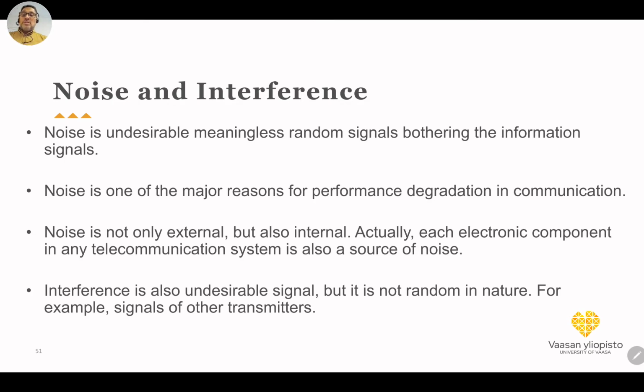But the difference between interference and noise is that interference, sometimes we can deal with it. So we have some interference cancellation techniques. For example, interference might come from a certain direction of arrival, so we can use beamforming to reduce the signal coming from a different direction than our signal, or we can use successive cancellation techniques, because the interference itself has meaning.